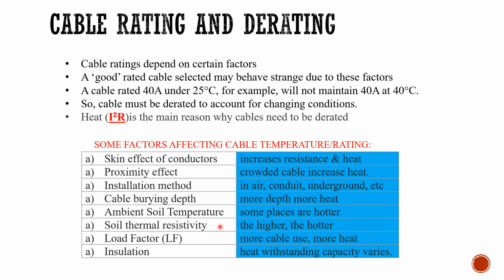Soil thermal resistivity. This is the inverse of the soil conductivity. If the soil is thermally resistive, it means it's not easy to dissipate heat via this soil, which means that the higher the thermal resistivity of a soil, the hotter the cable will be when it is buried in such soil.